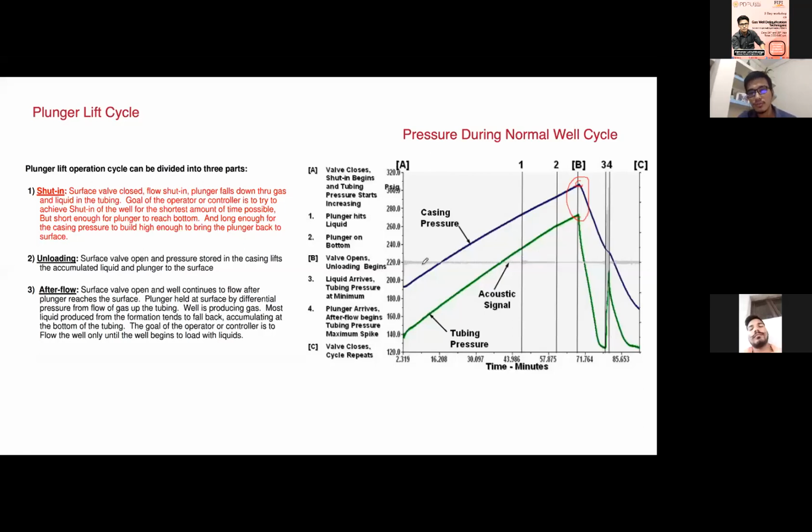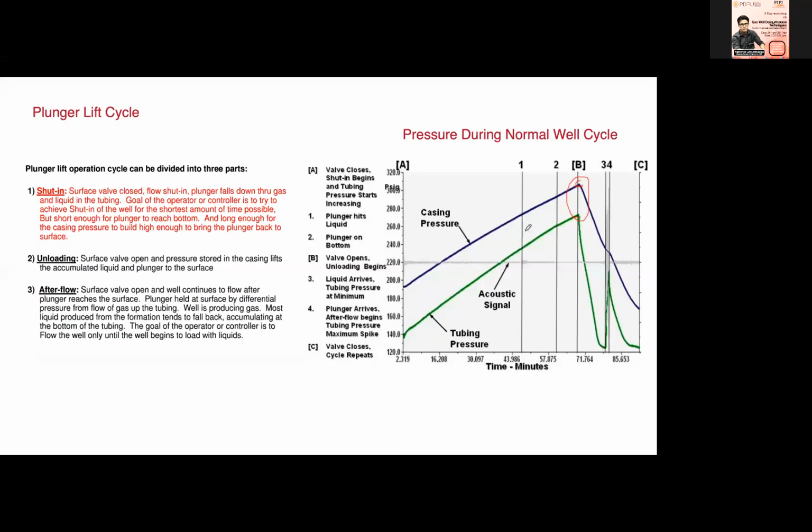You are going to monitor your plunger fall velocity. Will it hit the bottom? Will it reach the bottom? At what time did it reach the bottom? So that you will be able to determine how many cycles you need per day for your plunger lift.